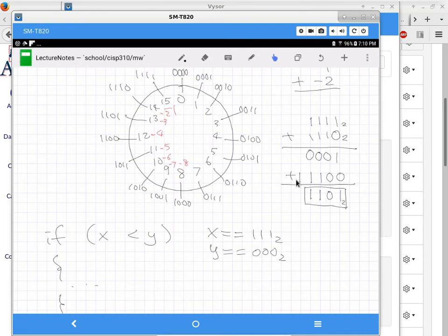So that extra carry bit, since it's only 4-bit, that would be the carry out for the 4-bit. But if it was in a 5-bit, wouldn't that carry be part of the actual sum? If it's a 5-bit adder, then you would have 5 bits as the input numbers, 5 bits for the sum, and then you will have one extra carry bit over here. Now it may not have a value of 1, but there's an extra carry that you have to specify. So my point was that if you perform this calculation on a 5-bit, then the sum would be 1110 and not 110.